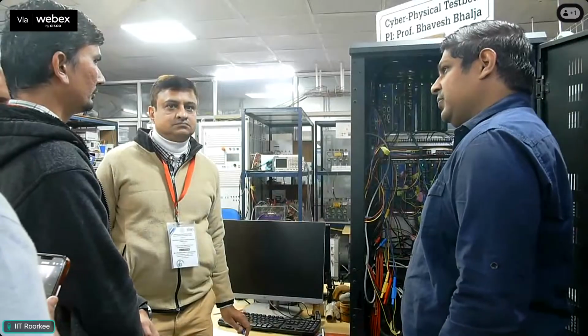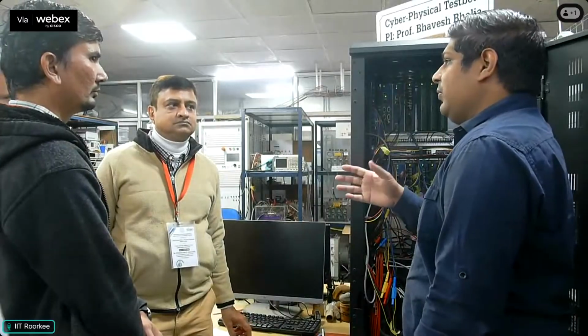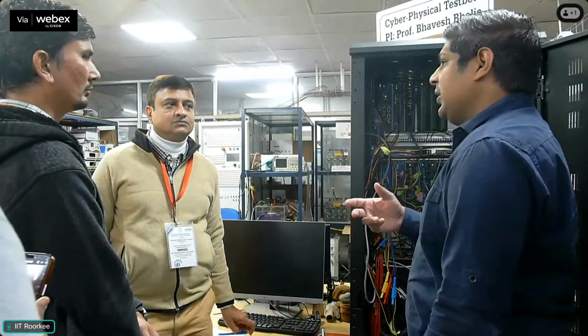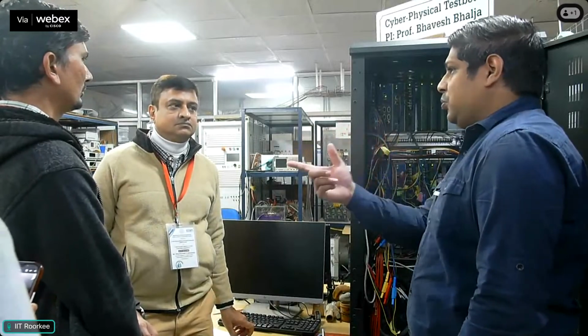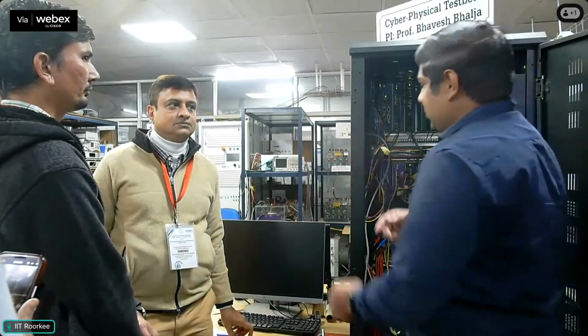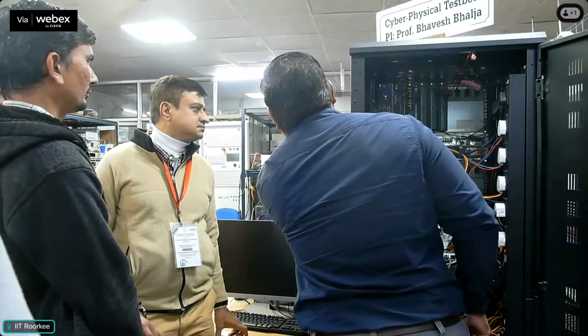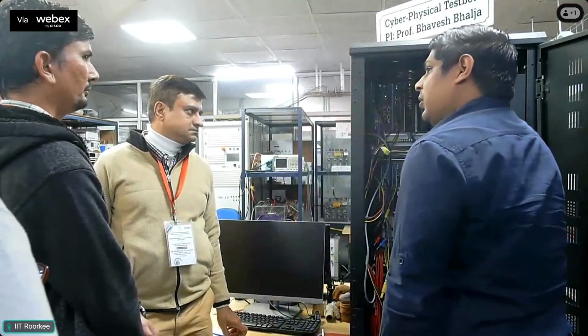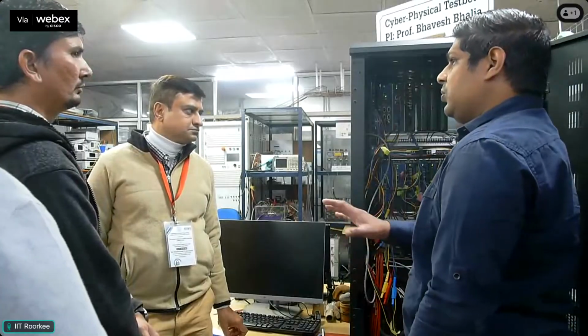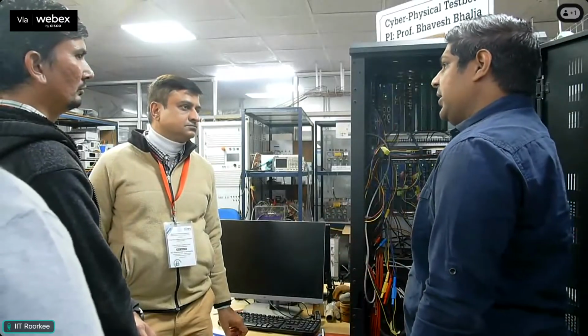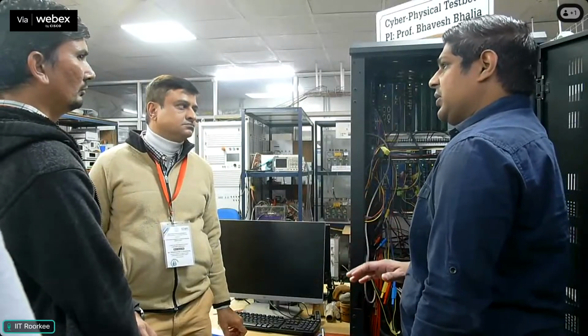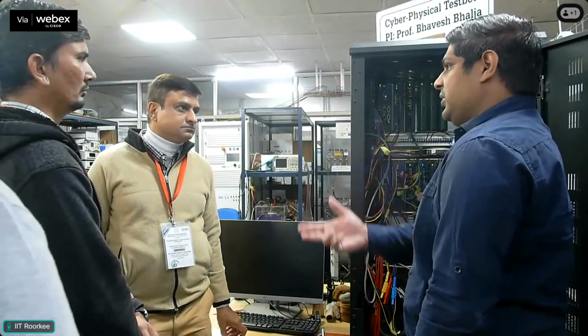So we will be simulating this attack tomorrow. Today we will just see how we can set up a wide area monitoring system. We will see one PMU to PDC connection. I will show you how we can see the waveforms in the monitoring software, and the GOOSE communication also we will see. We will trip. So this HIL loop we will see today. Just how the data looks like, synchrophasor data and GOOSE data, we will see in Wireshark today only, and attacks we will see tomorrow.